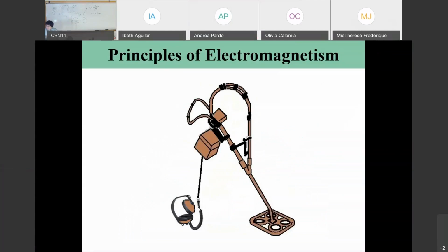By sending a current through a coil inside the metal detector. And then when the current stops, the magnetic field dies very quickly. This induces a current also in the coil because we are changing the field. This is how you monitor that change in magnetism, which is due to metals. That's how metals are detected, by magnetic pulse and a change in the current, and therefore in the magnetic field. And the pulses are detected by this metal detector.